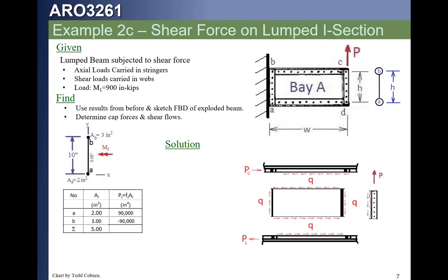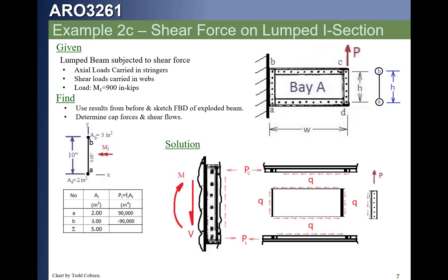So we have the force P acting on that vertical stiffener, and it's resisted by this Q. So if we sum our forces vertically, we'll say P minus Q times H equals 0, and we will find the exact same value of the shear flow as we did working from the caps. If we didn't, we have an error. In fact, we could have just summed forces on this vertical member to calculate the shear flow on the web, and then calculated the change in the force in the caps by summing up the forces using that value instead of the other value.